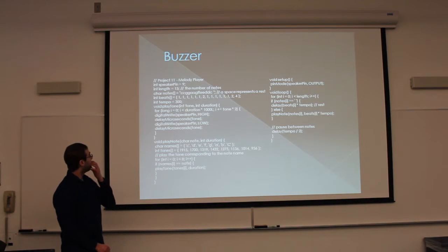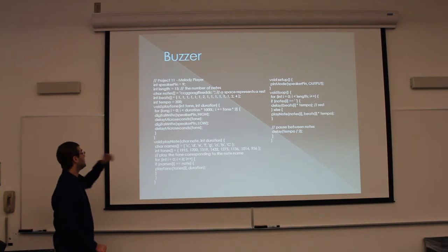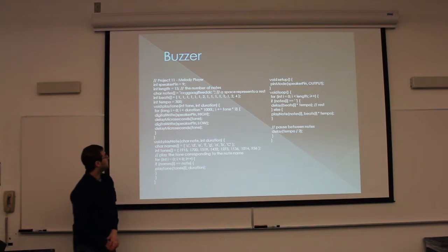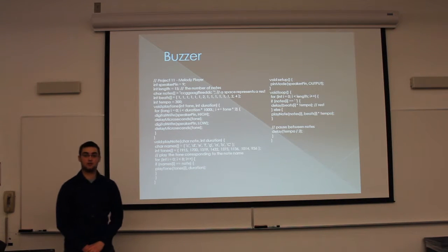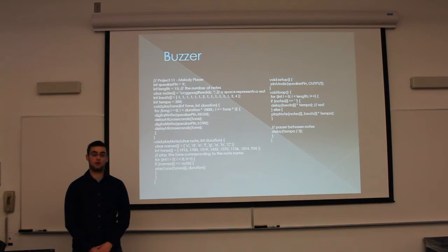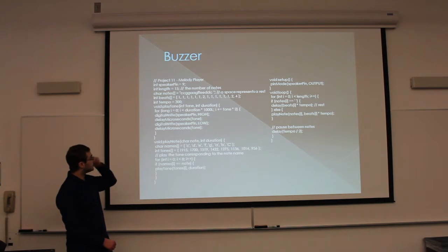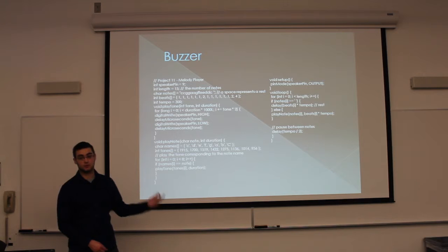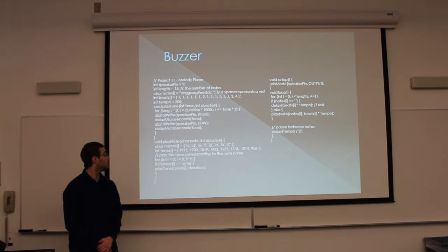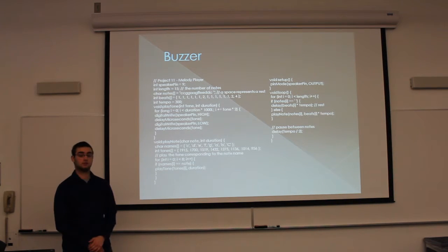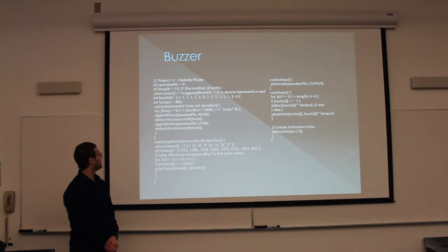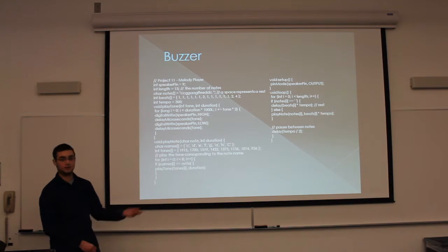The important thing here is the character notes and the int beats, which are up there. The character notes tell the Arduino what string of notes you actually want to play. This song is Happy Birthday, or Twinkle Twinkle Little Star, however you want to think of it. The notes on a piano are C, C, G, G, A, A, etc.